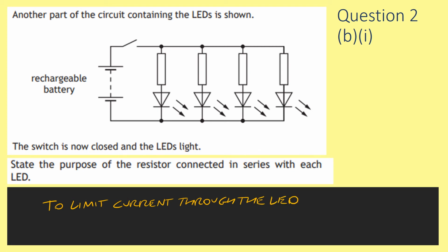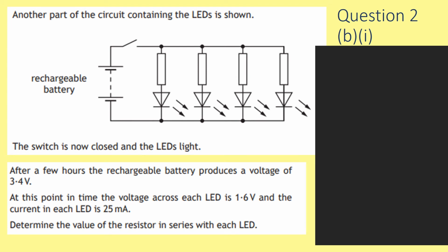We could also say, as well as limiting the current, it also limits the voltage across it. Effectively, we're limiting the amount of energy that the LED gets so it doesn't overheat.